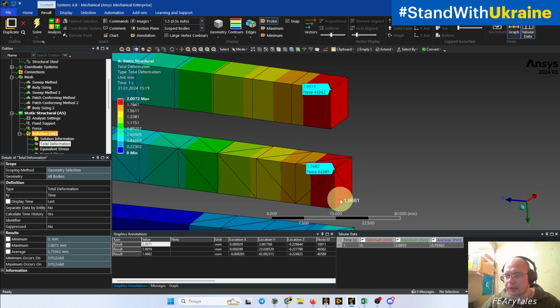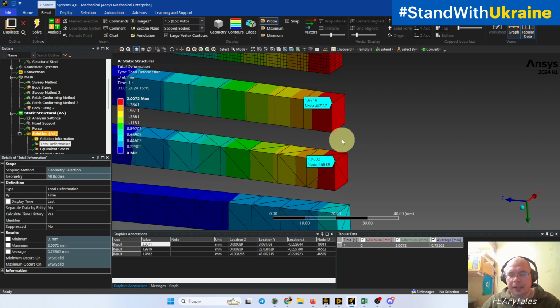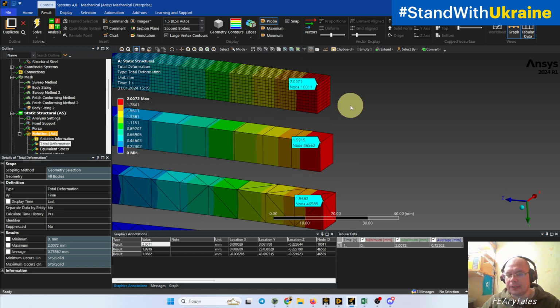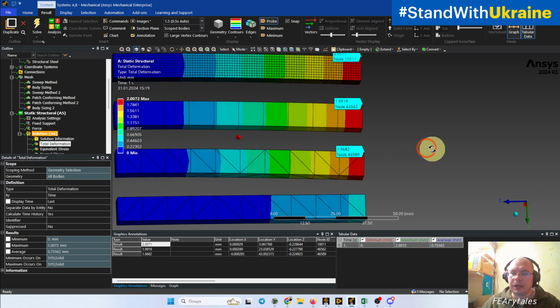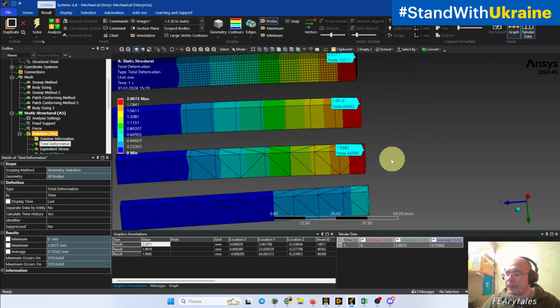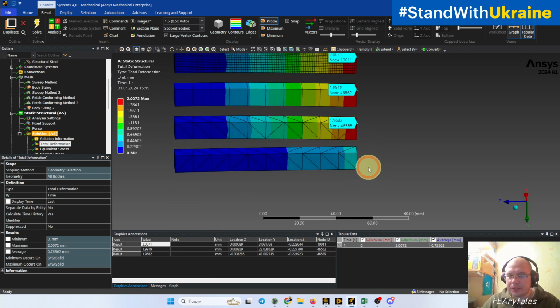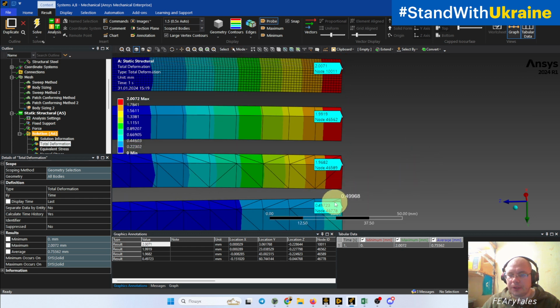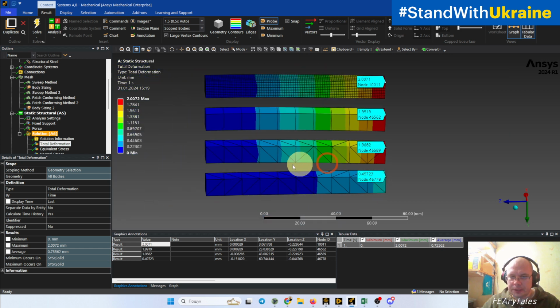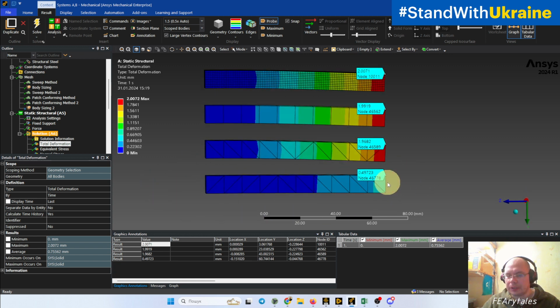So it's around 3%, and less than 1% of difference. So all three of them have the same accuracy for this mesh. And this last one has 5 times less displacement than the previous three. That's why it's very inaccurate, and that's why we need a much finer mesh to obtain a good result.